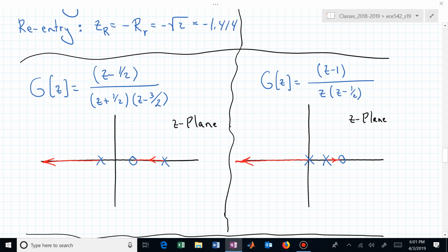And what's our pole zero excess? 1. So our asymptote will have an angle of 180 degrees divided by 1. What happens for large values of k is given by the asymptote angles. Here we just have one asymptote, so for large values of k, we're just going off to -infinity. And we have no action of our branches of the root locus off of the real line.